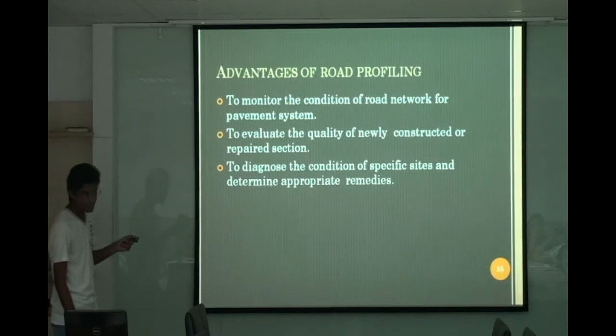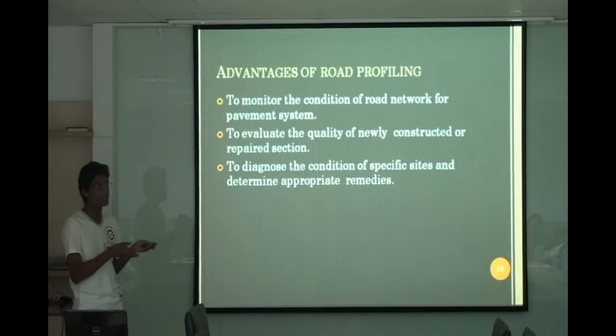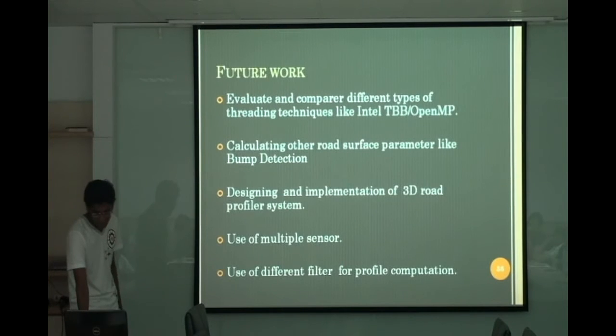Advantages of road profiling: to monitor the condition of the road, that is, how rough it is. So we can say that if the value of IRI is more, then the road is more rough, not smooth. It is also used to evaluate the quality of a newly constructed road or a repaired section, and to diagnose the condition of specific sites and determine appropriate remedies.